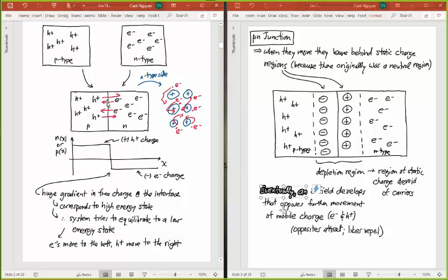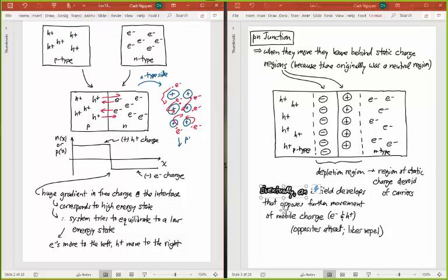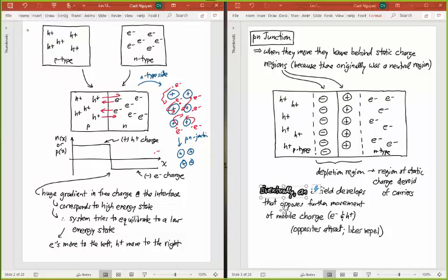And so after the p-n junction is put together, so let me go to blue again here. When I create that p-n junction, what happens is I'll have these atoms here that are still positively charged, and the electrons have left. The electrons are now somewhere back here on the p side, and they've been combined with holes.